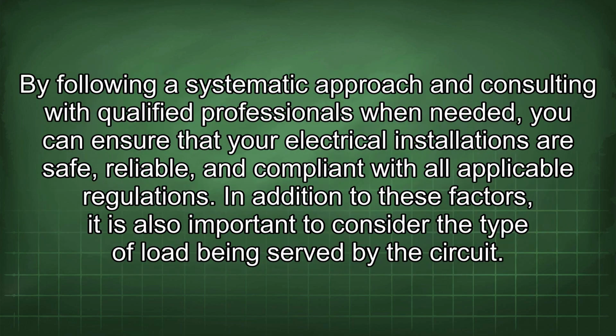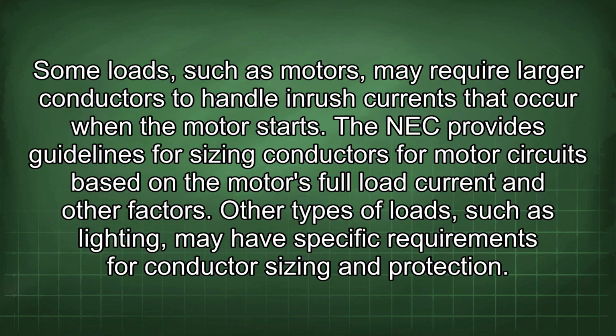By following a systematic approach and consulting with qualified professionals when needed, you can ensure that your electrical installations are safe, reliable, and compliant with all applicable regulations. In addition to these factors, it is also important to consider the type of load being served by the circuit. Some loads, such as motors, may require larger conductors to handle inrush currents that occur when the motor starts.